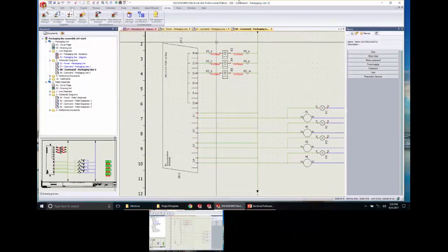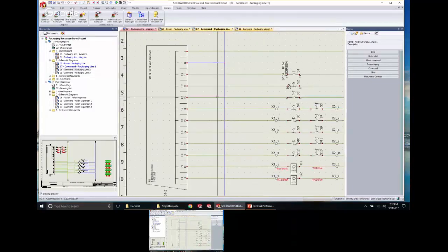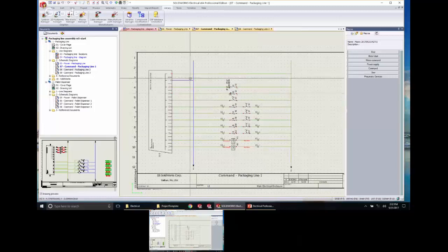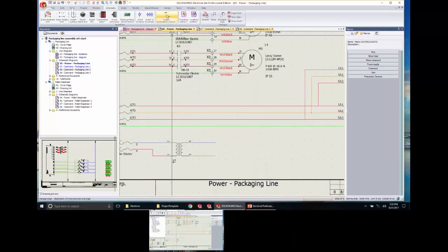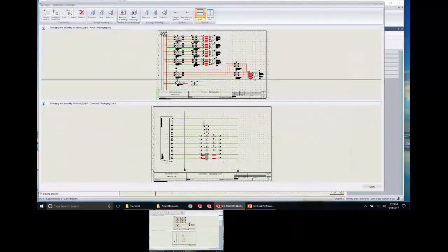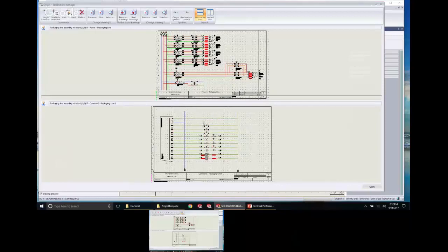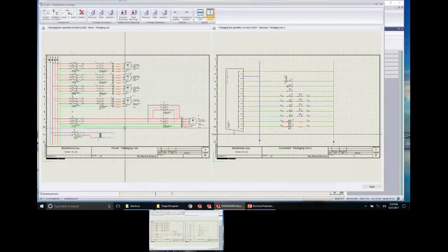But what I want to do here is hook up the blue wire and the green wire from over here. So what I'm going to use is under the schematic tab, this origin destination arrows here. I'm going to turn that on. Puts the drawings top and bottom. I like to look at the vertical tiles side by side.